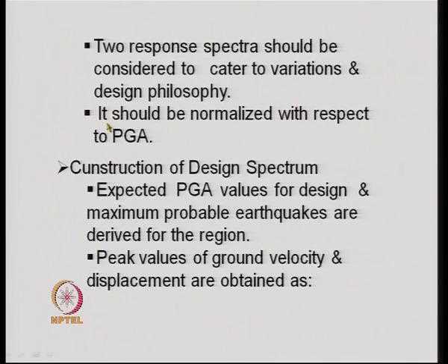And next is that the response spectrum should be normalized with respect to peak ground acceleration, because if you want to prescribe a design response spectrum, that should be prescribed in the form of the shape, but the actual response spectrum would be obtained after we multiply that shape with the peak ground acceleration, which may differ from place to place.